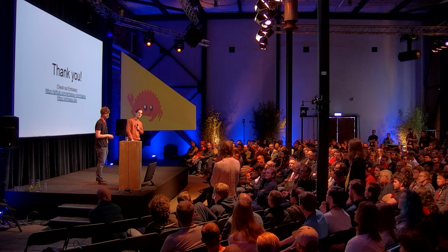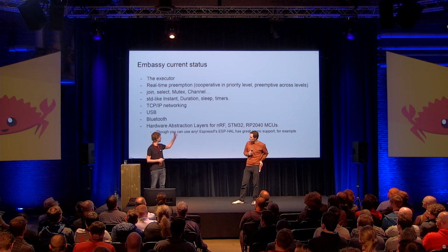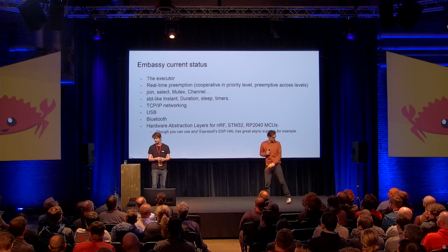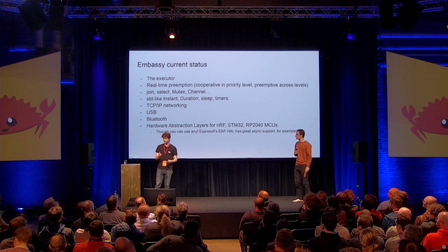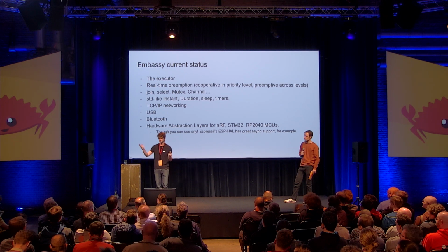One nice thing about an RTOS is the ability to have hard deadlines. How would that work with Embassy? Yeah, so I've glossed over it a bit, briefly mentioned it here. Async is purely cooperative. So if you have two tasks and one task wants to run, for example it got an interrupt, and another task is running, it will have to wait for this task to finish.